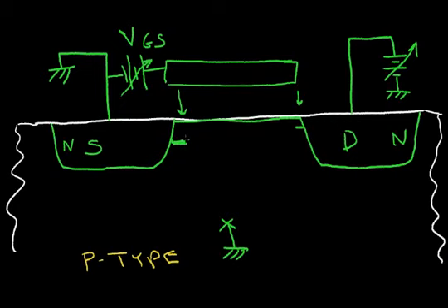So if I plot my channel, at the source I have a deep channel, then at the drain, the channel is not as deep anymore. So on my current versus voltage curve, my resistance is increasing. As the channel was driven down very far, it had lower resistance, but as this region is thinning down here, the resistance is increasing, and I'm diverging from this curve. I'm going to a little higher resistance, so this slope changes.